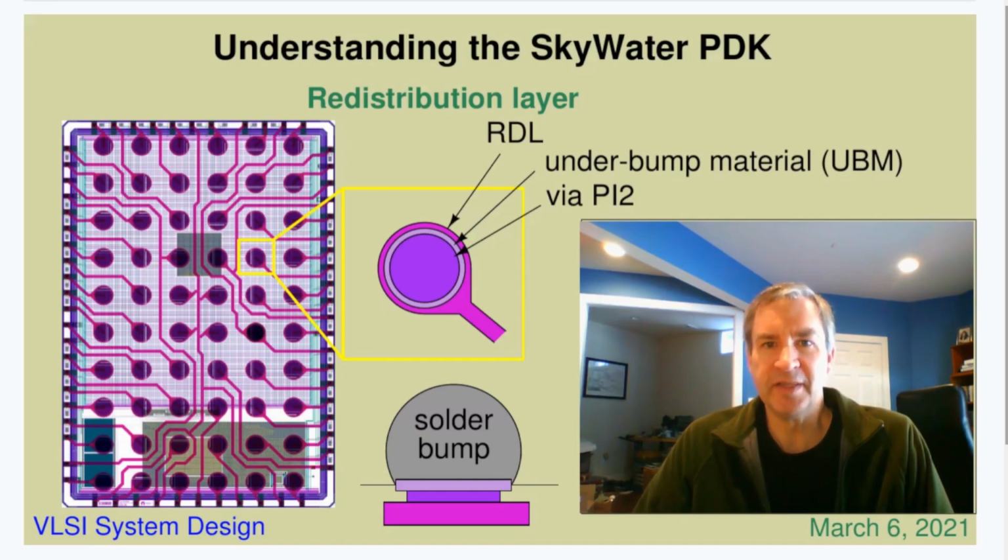The end result is that the die itself becomes its own packaging. No wire bonding is needed. The chip is just flipped upside down and soldered directly to a circuit board with the reflow process. The solder bumps are typically around 1/4 millimeter in diameter. This is a bit smaller than a typical BGA, or ball grid array, package.